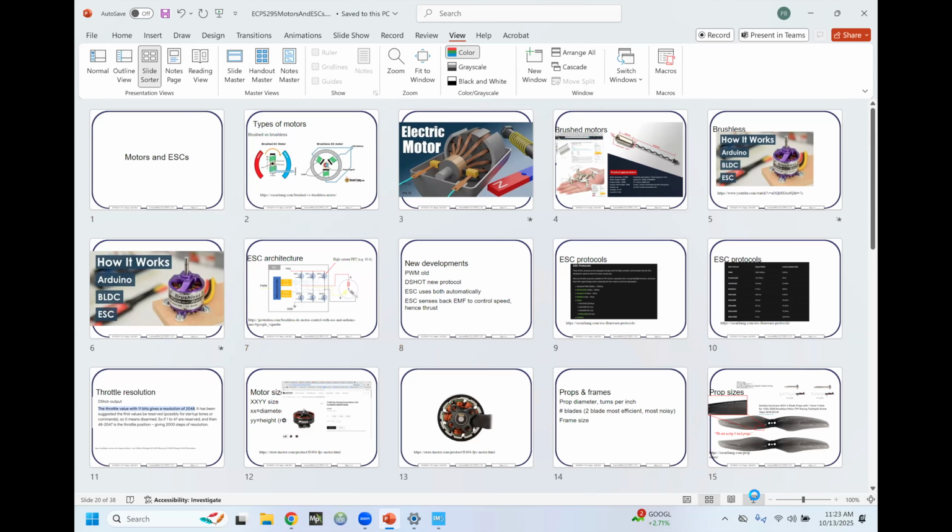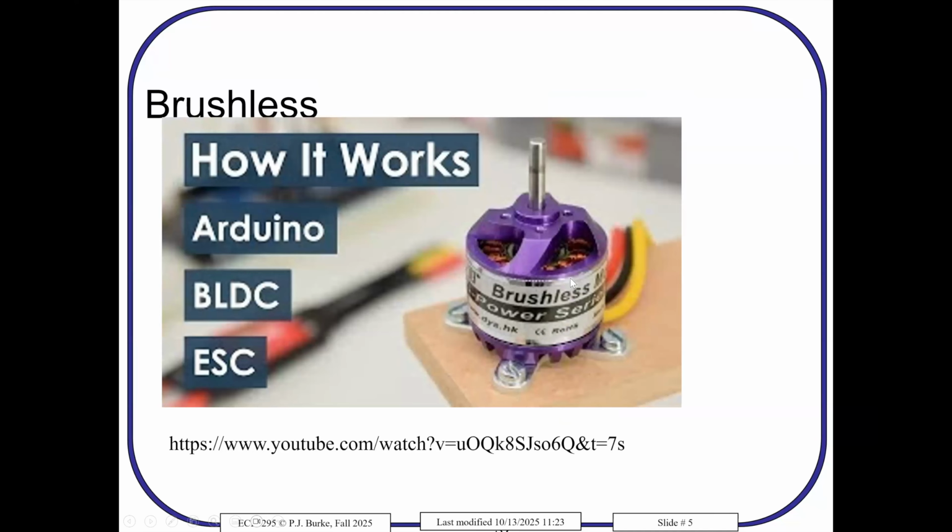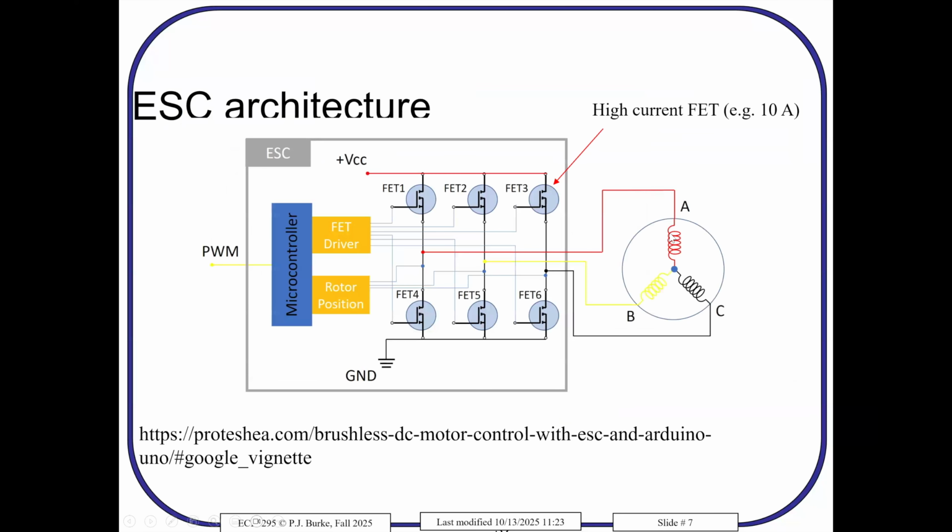Okay, so PWM is easy. It's common. However, it's an analog protocol. It's the pulse width in milliseconds that's being used to transmit the information. And it's a problem because there may be some noise on that analog signal. Anytime you have an analog signal, it's not immune to noise. A digital signal is immune to noise because if it's 4 volts, 4.5 volts or 4.6 volts, it's always bit 1. And if it's 0 volts or 0.2 volts, it's always bit 0. So a digital protocol is always very immune to noise. But here it's an analog quantity.